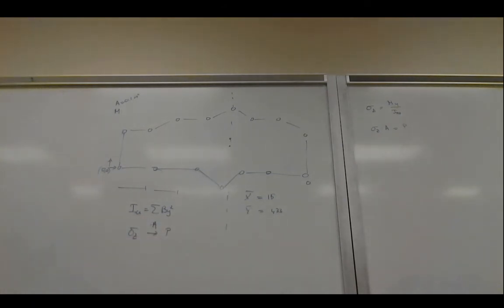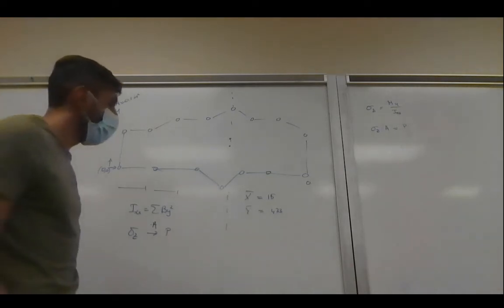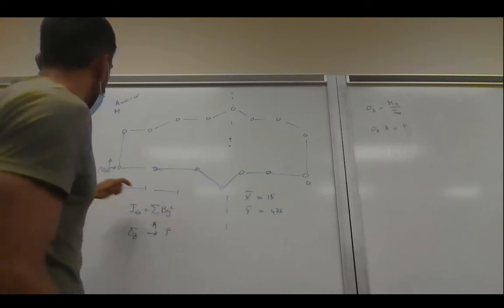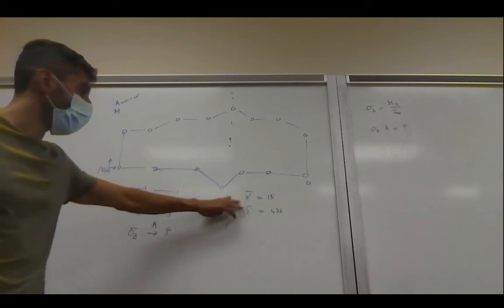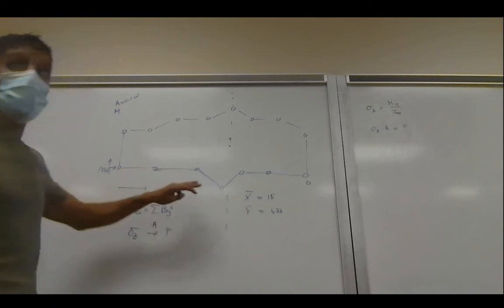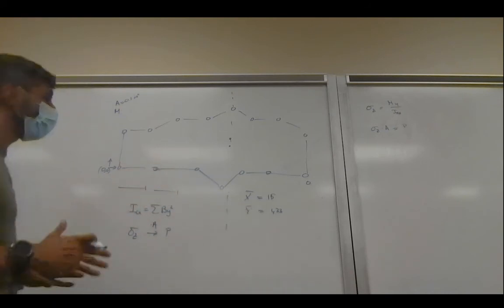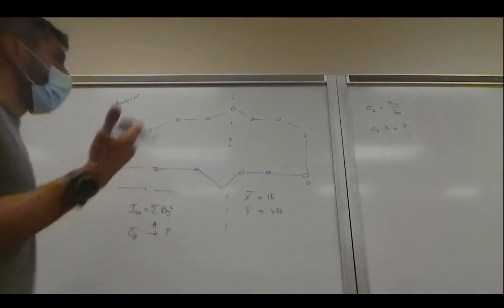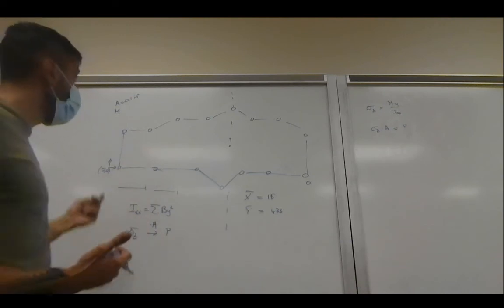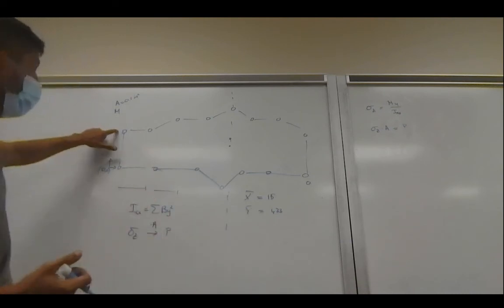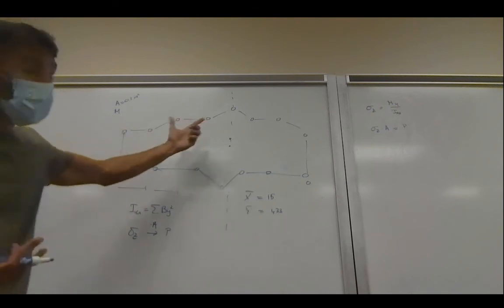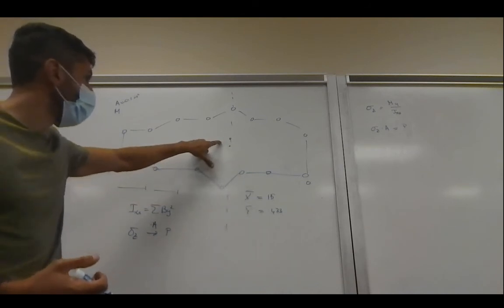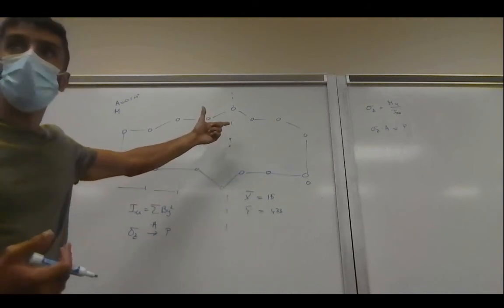So what most people did wrong, well, let me say first of all, when you calculate your moment of inertia, your centroid, clearly state where you're taking that centroid from. Most of the time I had to figure out, because some people got like a 7 or 8 number, and then for me it was hard to figure out where people start off at. Some start at this point, which is fine. Then you get just a negative number. That's fine. Some start from here, so they got instead of 4, I think 6.33.